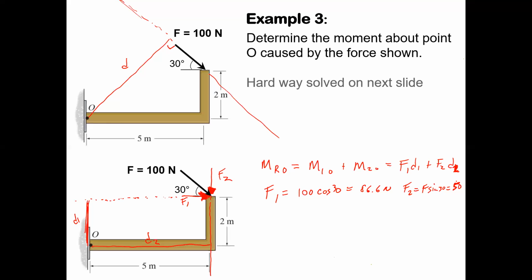But when you do the principle of moments to solve these things, the best way is not to get hung up on the signs of those things. It's weird, because normally you have to really worry about signs. In this case, you want to worry about the sense of the rotation that each of these forces is doing. And then the sign will come from the water wheel analysis of the rotation that that force wants to do around that point. So you can just basically forget about the signs of the forces, focus on the magnitudes and the distances, do your products, and then after you do your products, figure out whether the water wheel is going to be spinning clockwise or counterclockwise for each of those components. You see what I'm saying?